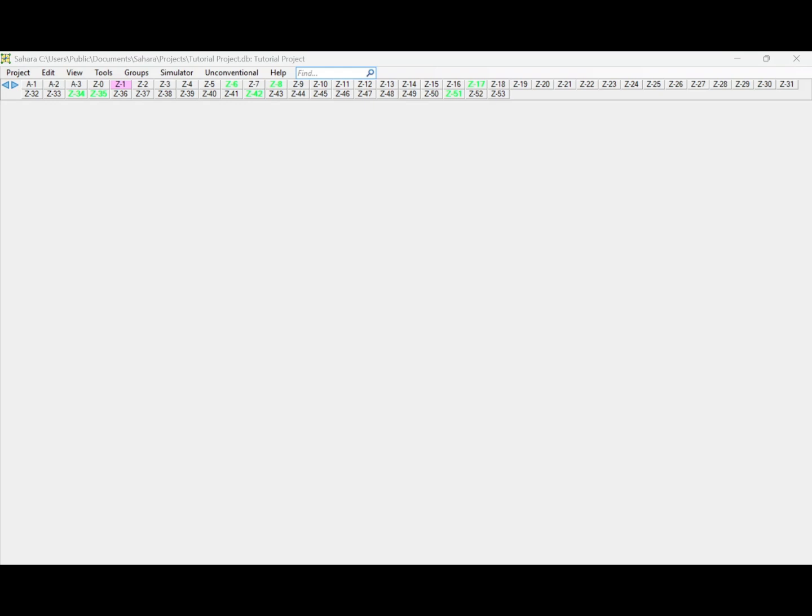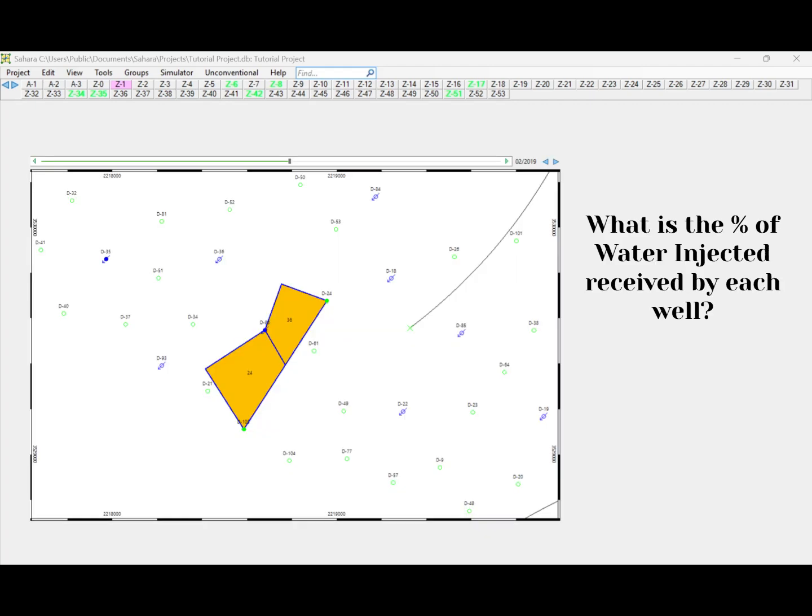All these calculation models will finally allow us to calculate the fraction of water as a function of the accumulated water injection. So we need to keep in mind that the methods always make the connection between how much water is being injected and how much oil is being extracted from the sweep of water. The different methods will not say anything about the water produced, like the total liquid produced. That is going to come from the coefficients associated to each different flow element. And again, we will discuss it in more detail in the future. This is just a general review before we start.